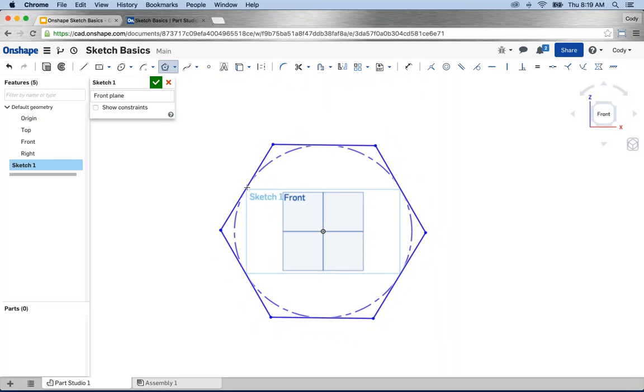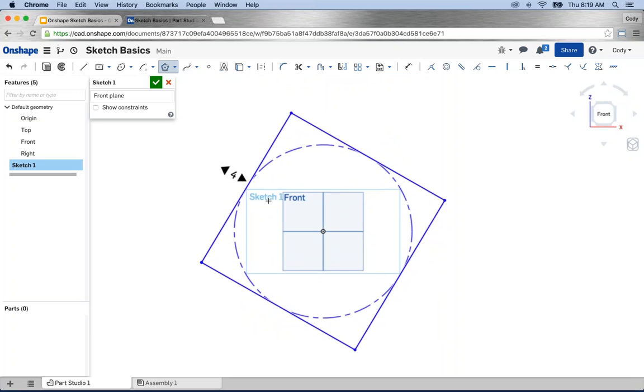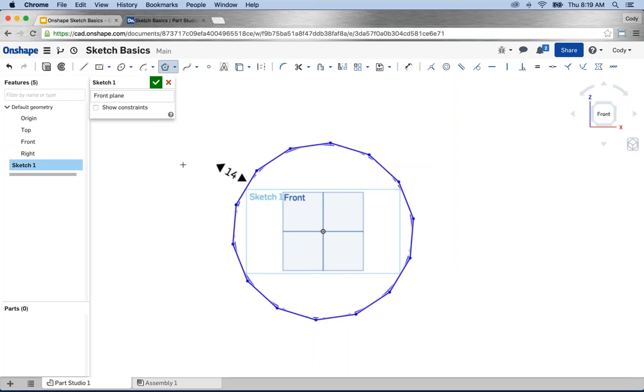appear, left click again, and here's the step that's easy to miss. As soon as you left click, you then move your cursor in or out to define the number of sides that the polygon has. So you can go all the way down to a triangle or as many as you'd like out. So just keep in mind you can set as many sides as you'd like.